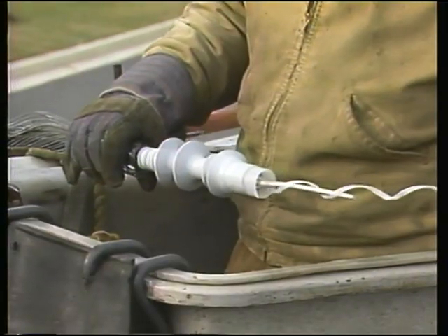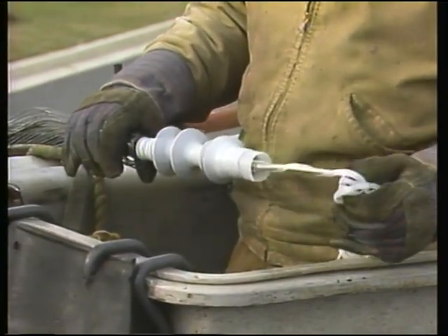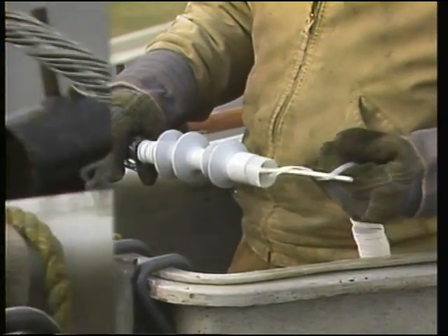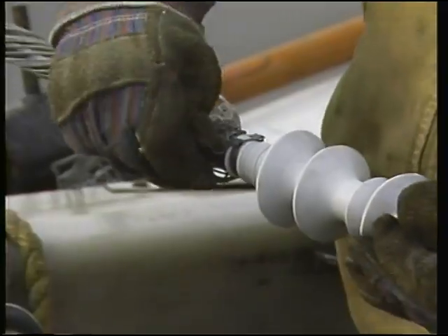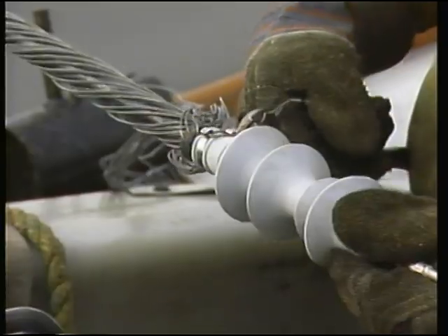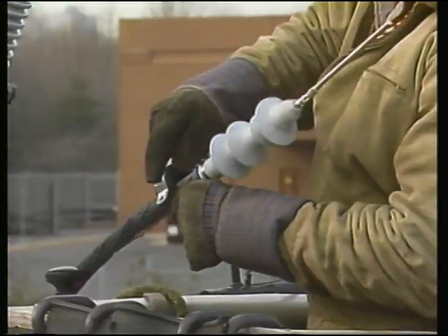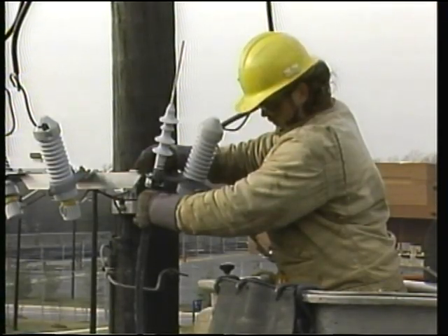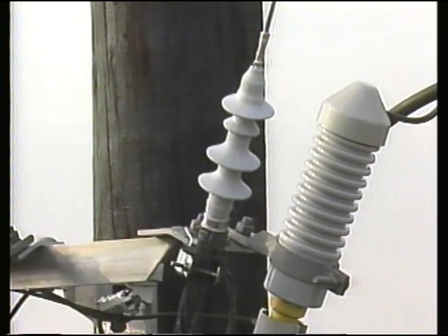The workman places the cold shrink tube over the insulation and applies it. He places the tube so that it butts up against the concentric wires. The last step is to ground the termination by connecting the grounding strap on the cold shrink terminator to the concentric wires. To mount the terminator, the workman installs a metal mounting bracket and then mounts the terminator. The result is a one-piece Class 1 termination that provides stress control, external leakage protection, and an end seal.